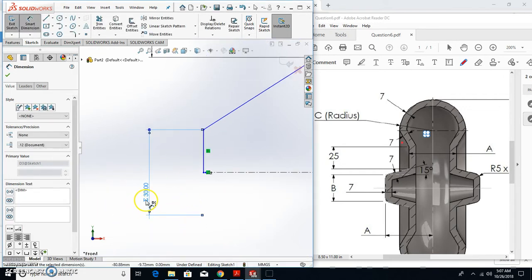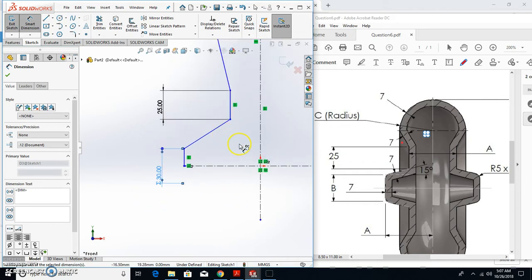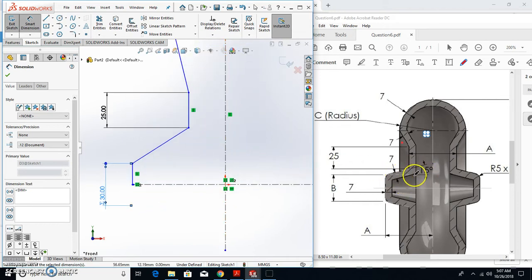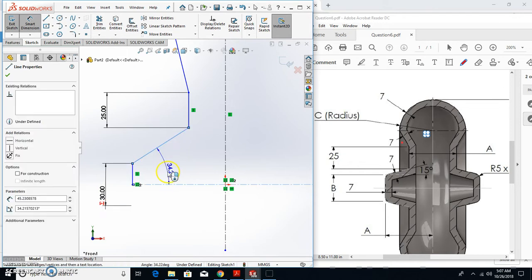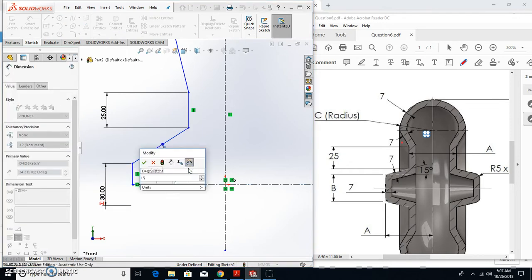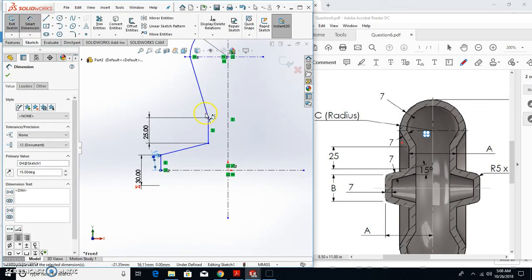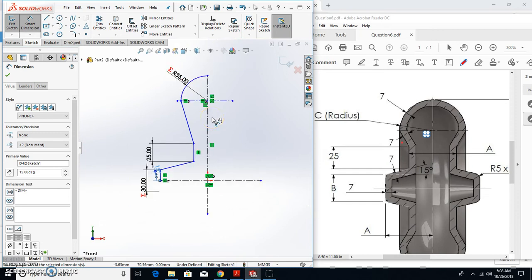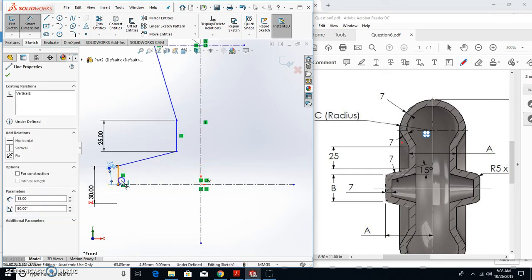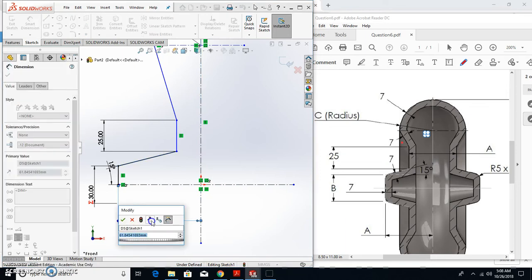Alright, so you know that that's set to an equation. Alright, so we got a 15-degree angle here, so that's basically 15 from horizontal, so I can go off here or I can go off a reference line, so I'm going to go here to there. That's 15. And then we'll start setting some of our diameters. So A here is from there to there, so A is from there to the center line. It's A equals global variables.